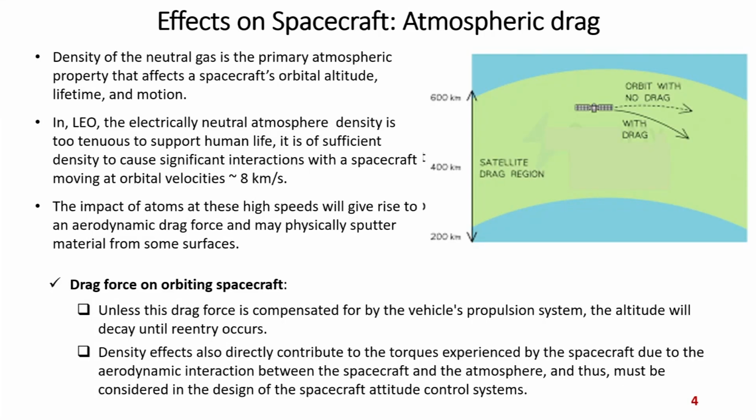So, the yaw axis should ideally point to the center of the earth, but because of the torque it may deorbit. In that case, the satellite link and the wireless communication system will be out of line of sight, and the satellite cannot be operated. So, all these things are corrected, as you have already seen in the satellite segments, by the attitude and orbit control system. In the attitude and orbit control system, the satellite's orientation as well as its orbit is corrected, which is called station keeping.